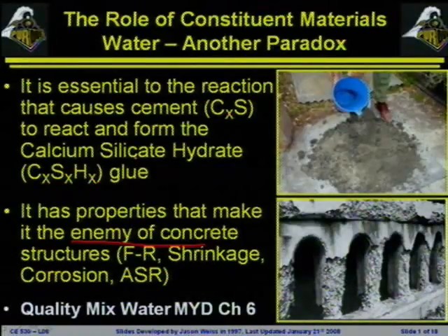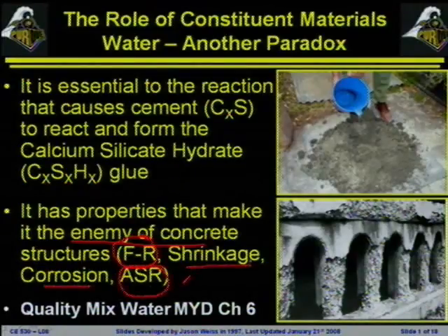So if we think about a lot of the ways that concrete can fail, if it fails due to freeze-thaw damage, alkali-silica reactivity, corrosion, or shrinkage, there's typically an aspect of this that has water right at the forefront. Freezing and thawing: if you don't have water inside of the concrete, that water can't freeze and expand and can't cause the problems that we have with freezing and thawing. So water is directly responsible there.